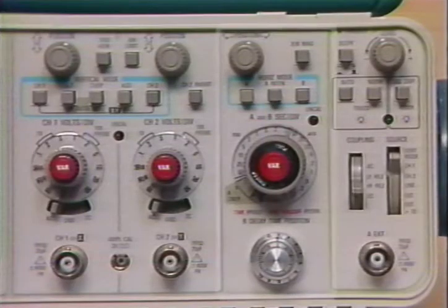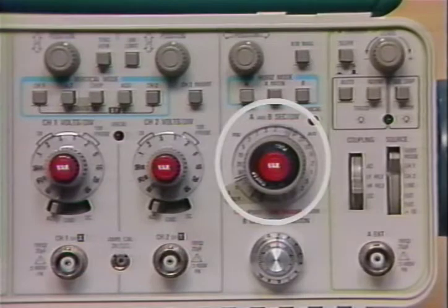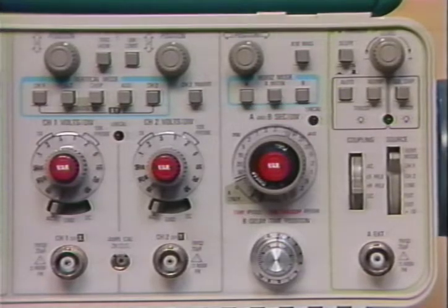The horizontal system controls horizontal movement, the x-axis. It uses an accurately timed sweep waveform that moves the beam in a constant and linear fashion horizontally across the CRT. This allows time measurements to be made on events applied on the vertical axis. There is also a horizontal position control and a way of connecting vertical channel 2 to the horizontal system for special XY displays.